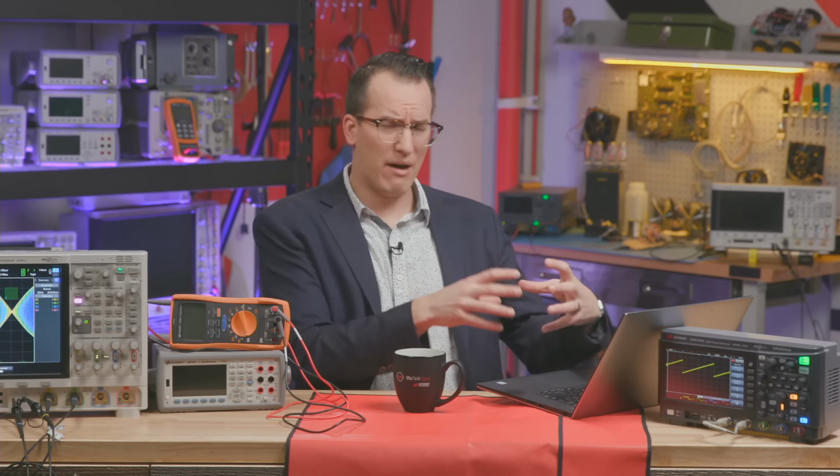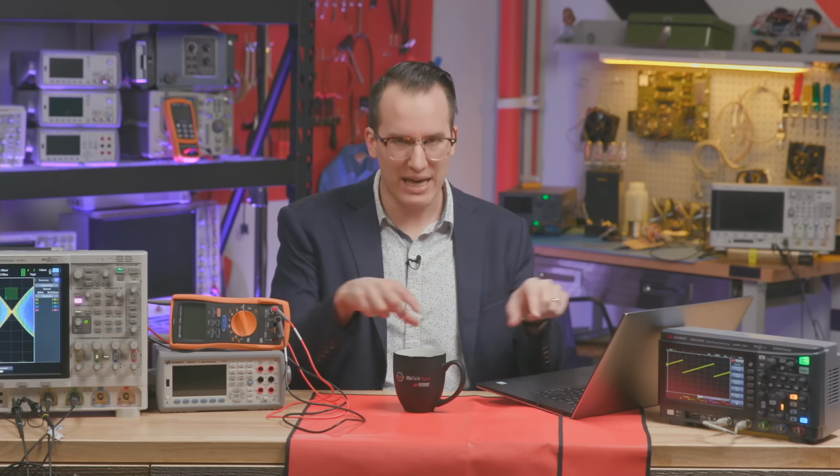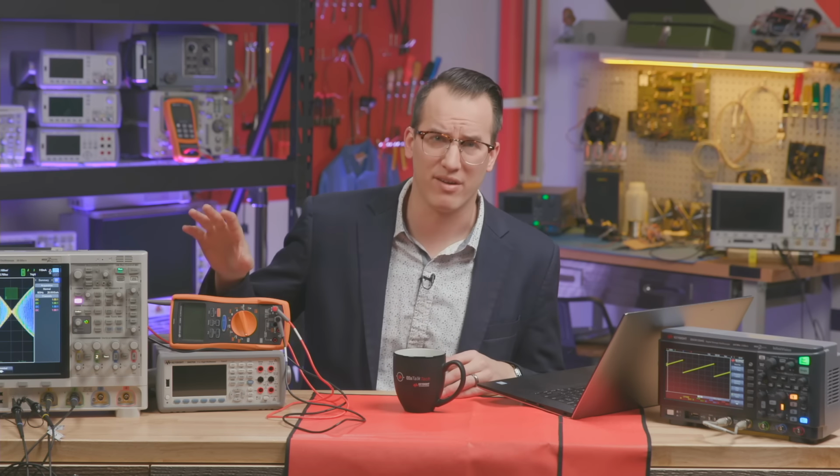The ground of your scope is tied to earth ground, but we do a lot to make sure that the actual power converter from AC to DC in the scope gets a really clean DC output. It goes back to measuring power rails and measuring your power integrity. If you have ripple on your power rails, you're gonna have noise in your system. So we do a lot to clean those signals up and clean that power up as it comes in. But you know, the power that you plug into does make a difference.